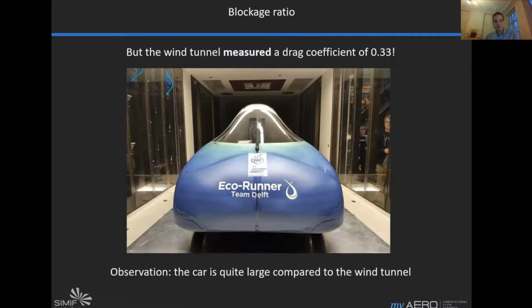So now for the wind tunnel test, we measured a staggering drag coefficient of 0.33. So that's like 60% higher than what we were measuring in CFD. That's a huge difference. And we were quite stunned by that.